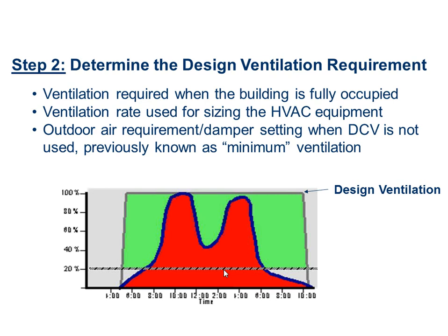I say approximately because it's really a function of the ASHRAE standard and the IMC. Like you heard me say before, we need 5 CFM per person and 0.06 CFM per square foot for an office building. The 0.06 CFM per square foot is to take care of the space VOCs, so off-gassing of furniture, carpeting, etc. The 5 CFM per person one is the one I'm allowed to modulate.